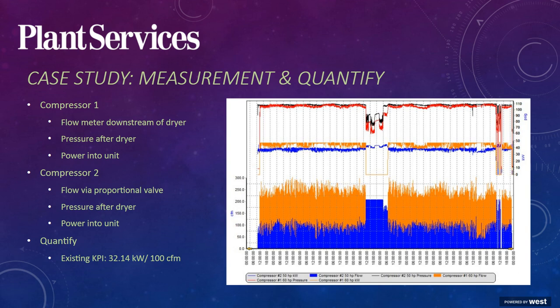If I simply said measure flow, power, and pressure like that last slide, what would you think of? So, now you have a visual. And now we have a graph. We can see that flow is on the bottom, broken out for each compressor in 2 different colors. Power is shown in the middle for each compressor, again color-coded to match the flows. And then the pressures in the 2 sides of the plant, 2 rooms, are at the top.